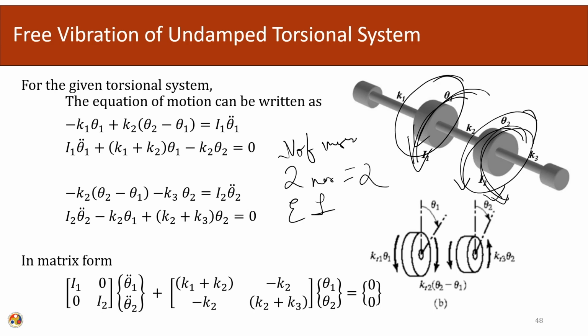Okay. And the rotational stiffness is being given by K1, K2 and K3. Okay. Earlier K1, K2, K3 were giving the translation stiffness, now K1, K2, K3 are giving the rotational stiffness. Okay. And earlier there was M1 and M2 which was giving the effect due to the inertia. Okay. Now, there is I1 and I2 which are giving the effect due to the rotational inertia. Okay. So, similarly we can write down the equation in a similar fashion. Okay. So, the equation of the motion for this rotating mass can be written down in a similar fashion, getting the same analogy from the translational springs.